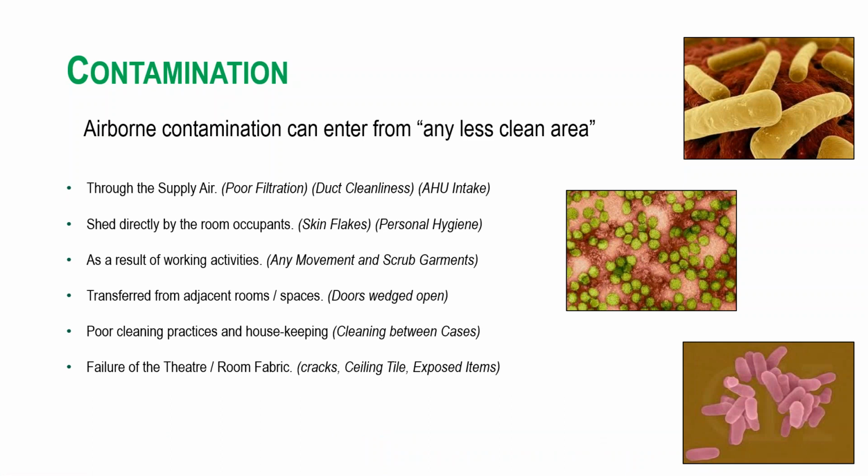Really what contamination is by definition is an outside vector or an outside material that contaminates or gets within a space where there are active participants or an active production. And how airborne contamination can enter is very straightforward. I mean, it can go through supply air, it can be shed directly from room occupants through coughs, personal hygiene, etc. It can be a result of the process itself, transferred from adjacent rooms or spaces, which is not only doors being wedged open, but also natural leaks or holes or cavities within the lab space, which in a biocontainment lab should not be present, but in a hospital or something along those lines, they definitely are.